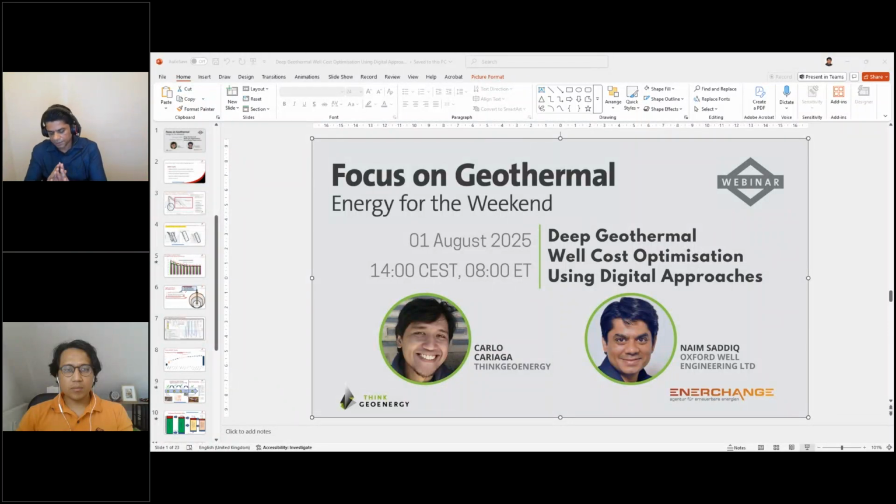But this is just one KPI. There are a lot of things that only automated invisible lost time analysis can find. There are technologies everywhere right now. Use the right one and comb through the drilling operations and find out which KPI has been consistently lagging or not efficient. Then you have a feel for how much time we are talking about, and then you talk to the people who actually can intervene and improve the rig affairs, for example, the tool pusher or the drilling supervisor. Tell them this is what you see. Show them the presentation of this data, and then things will get tidied up.